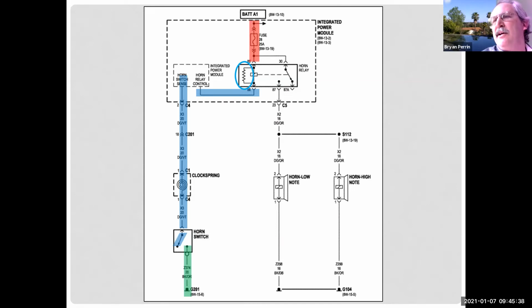It makes sense to go see, did someone forget to bolt it on the car when they worked on it? Did the wire break or get eaten or whatever? So yeah, absolutely. And the horn is an easy circuit to diagnose. And so we do that quite a bit. If I have multiple systems that aren't working, I'm going to diagnose the one that's easiest first, thinking that they're all probably related. So I'm going to go to the one that has the easiest test points and is the easiest to check out. So that's a great point.